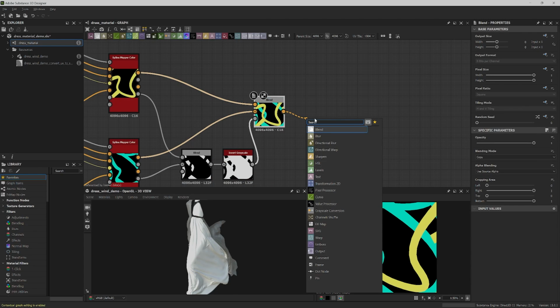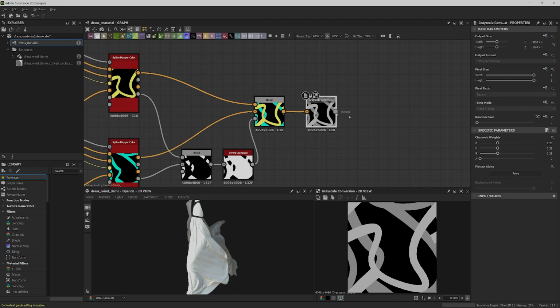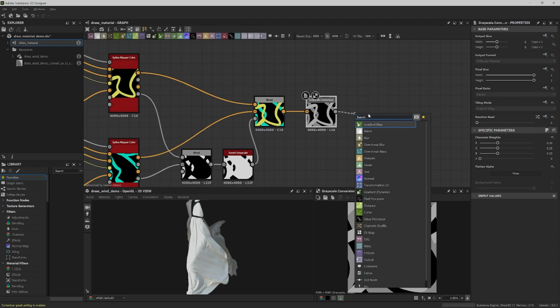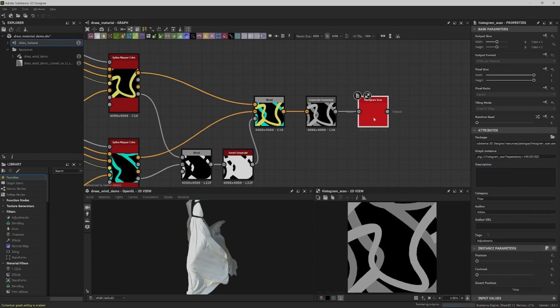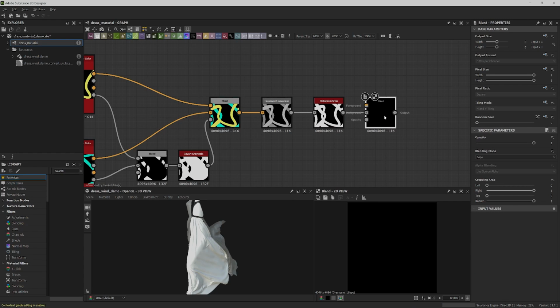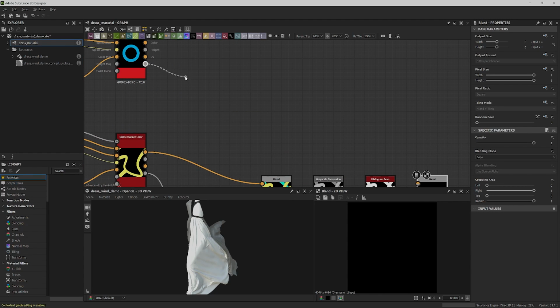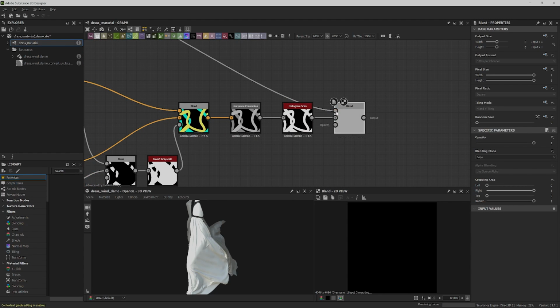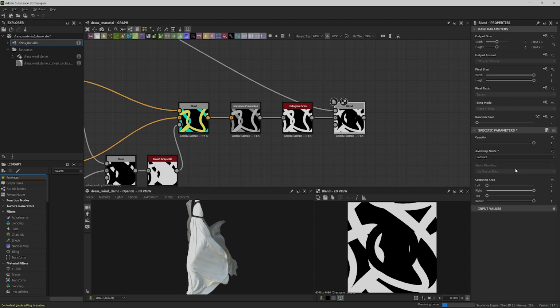After converting the final blend to grayscale, use a histogram scan to convert the design into a black and white mask by dragging its position parameter up to 1. Then, blend the result with the circle in subtract mode to subtract the circle from the rest of the design. This chain of grayscale nodes, after the last blend, will help create a mask for the next blend that we'll make.